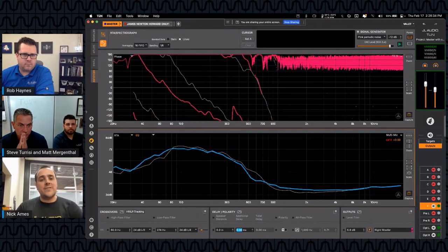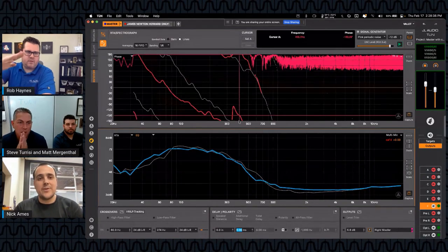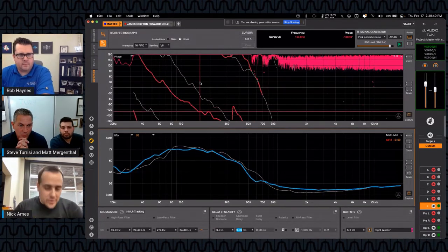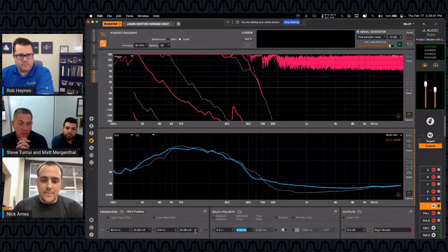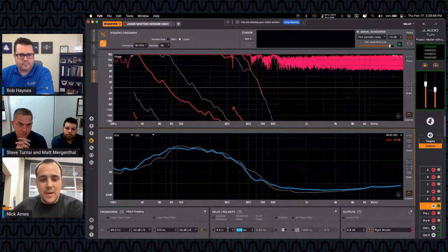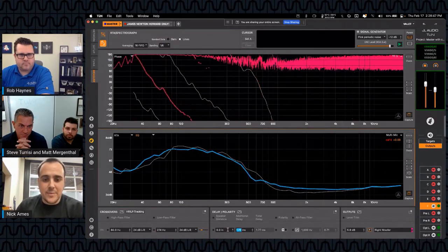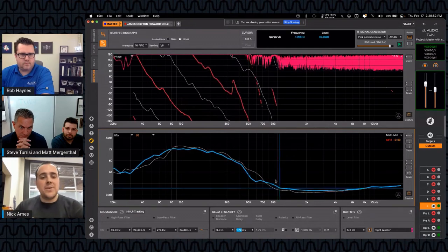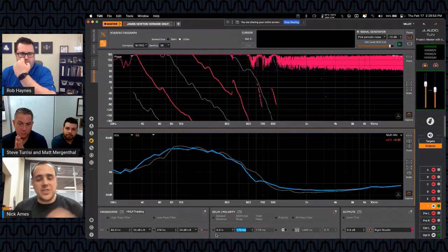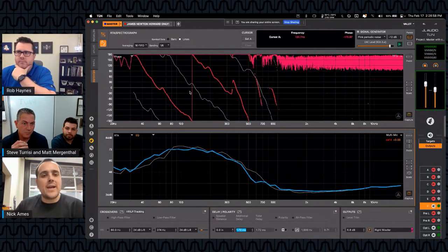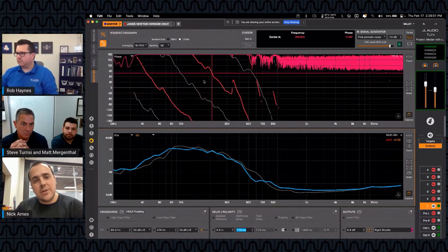okay, now see the angle of the phase slope of the red one compared to the gray. It's not the same angle anymore. So adding delay changes the angle of the phase trace. Yep, I needed that 1.72. Now that 1.72 that we put in, let me put it back in there. 1.72. Okay, so we put that in using the impulse response. We scooted them all over so they were all lined up at the same time as each other. So that got the timing pretty darn close here.